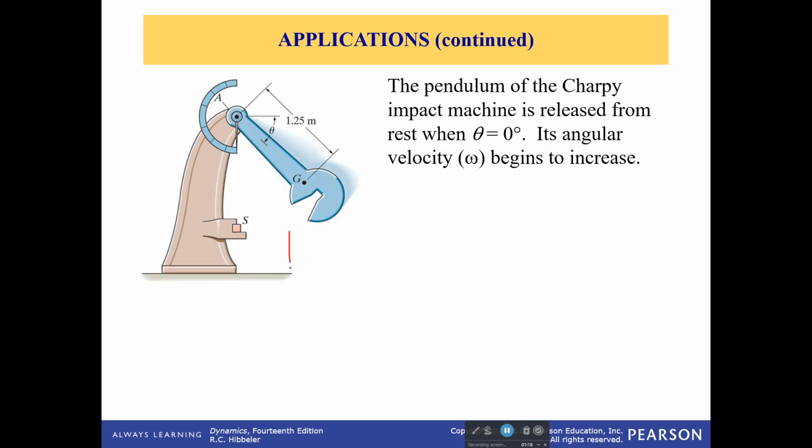Another thing is this is a Charpy impact machine. It's used to understand how materials, which are usually rectangular, are affected by super cold temperatures or being stretched, or by having a little chip in it. If I change the temperature, does it take less energy to break it? If I stretch it, does it take less energy to break it? If it has a little chip in it, does it take less energy to break it? And so you can understand more about it from that.